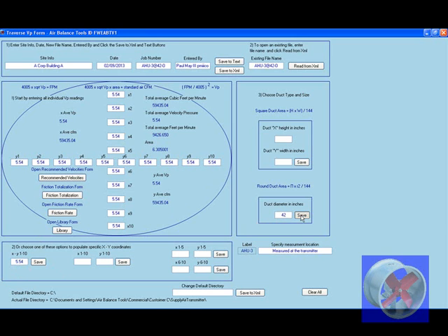So we can use this 5.54 transmitter in a 42-inch inlet of the fan, and we have to rescale our transmitter at our DDC or our controls, whether it's Johnson Controls, Allerton, ALC, or Siemens. So it's a 4 to 20 milliamp signal, and at 20 milliamps this transmitter in this piece of equipment is going to equal 90,695 CFM. In most cases, there is a calibration or an offset that you can place in the DDC system.